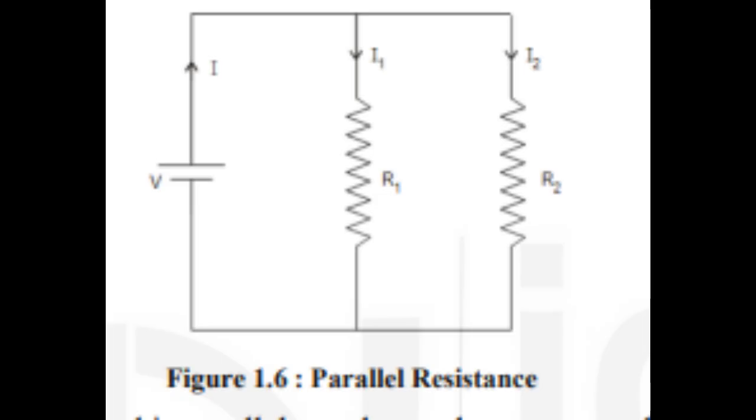1.3.3 Ohm's law. The opposition to current flow that exists in every material is called resistance. It is the property of material by which we know how it resists flow of current. The property which supports flow of current is known as conductance. The reciprocal of resistance, R, symbol for a resistor, is conductance, G. The resistance is measured in ohms, Ω.